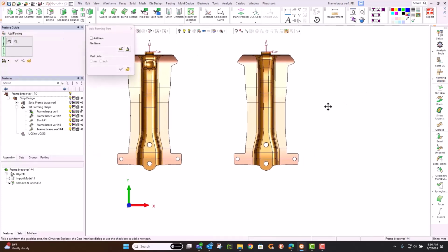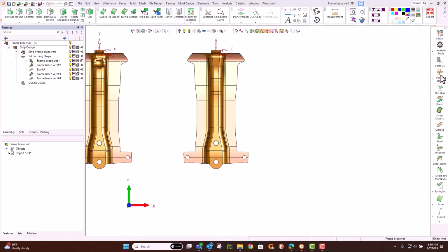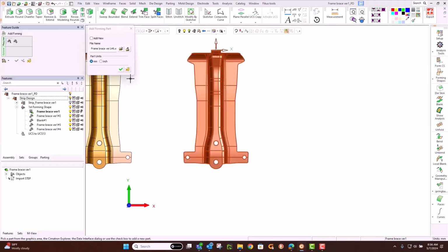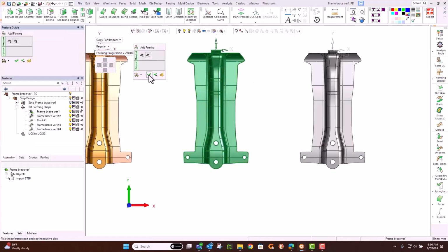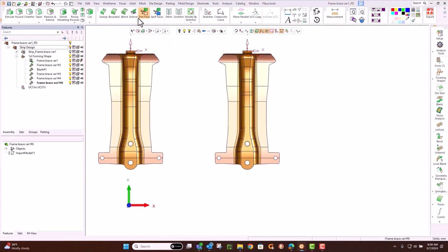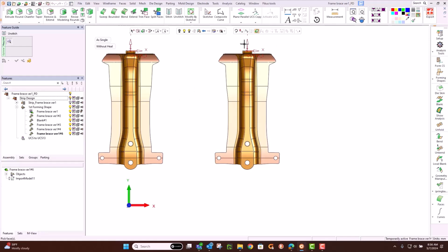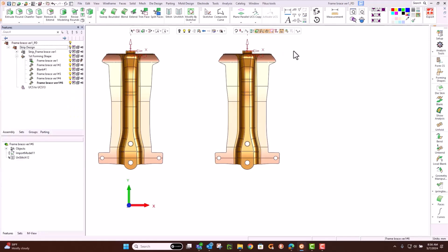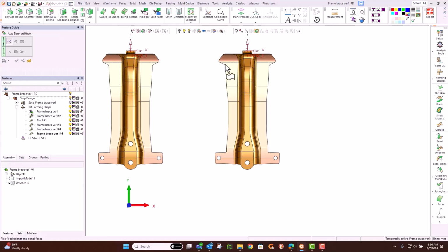Let's work to the inside of that groove. We want to develop the left and right hand sides again. So basically I'm going to keep that tab where I know I would connect my carrier. Here I'm going to select right down the center and say this is the area that I want to develop to. We'll pick the left side again and now develop it out like that.